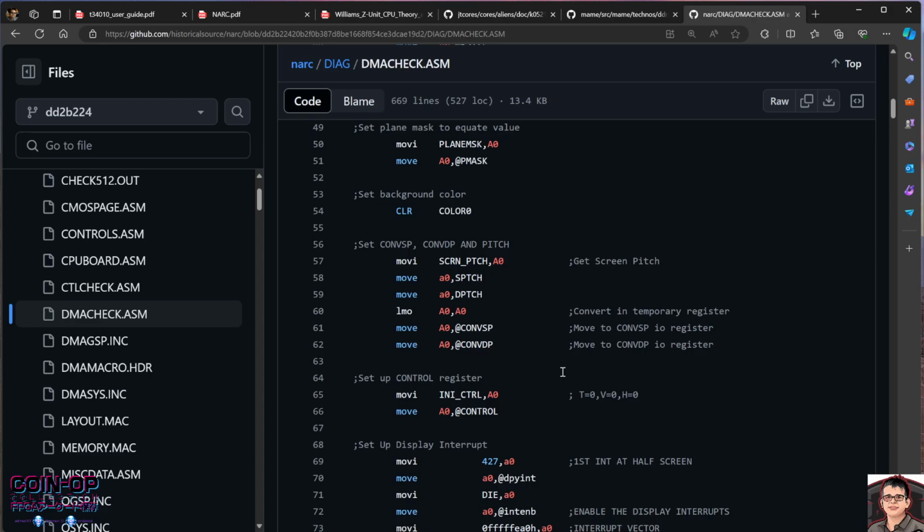There are literally video timings in the assembly code that it pushes to registers on the TMS, and then the TMS uses that to generate the video timing signal, which can be used to generate your line counters and all that stuff, and ultimately draw graphics on the screen. But what's interesting is this is pretty software controlled. There are no hardware sprites in this platform. It's all software, blitter based routines.